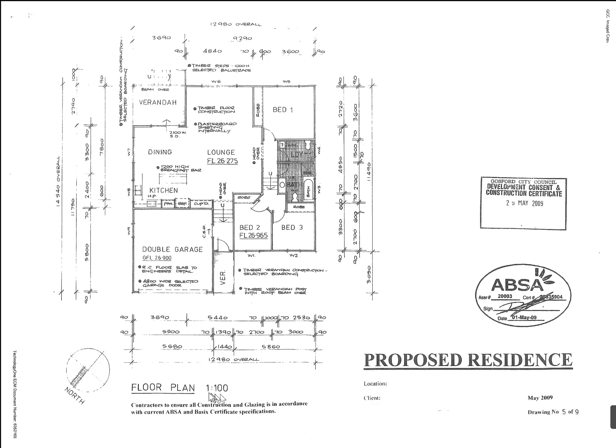The scale is 1 to 100. That means every millimetre on this drawing equates to 100 millimetres in real life. So the 3050 millimetres shown here would, if I was to measure it at a scale of 1 to 1, equate to 30.5 millimetres. If you don't have a scale rule and you need to draw something to scale, all you need to do is divide it by whatever the scale is, and that's what the actual millimetres are. We've got the same council approval, we've got the ABSA certified approval there.